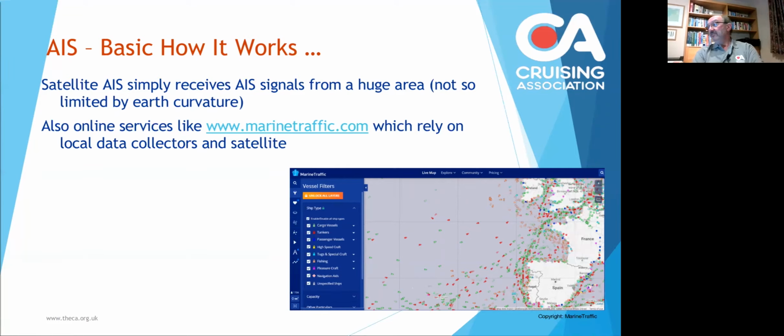And as we can see from the marine traffic image on the right-hand side, it's actually picking up ships right out in the middle of the Atlantic because the satellites are sufficiently low that they are within the range of the VHF. But be aware that that information is usually somewhat out of date. Typically, on average, about 90 minutes out of date.